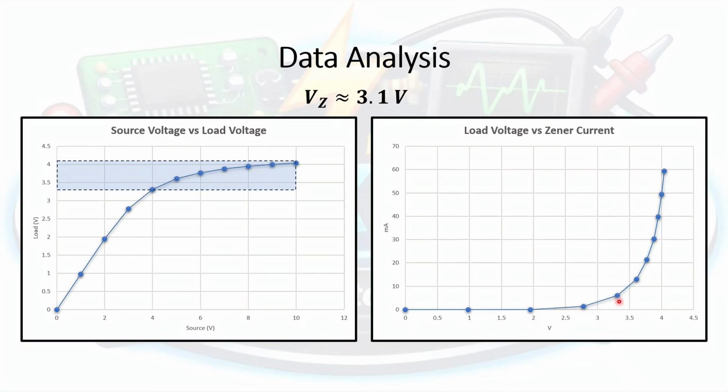However, when the voltage on the diode goes over the reverse breakdown voltage, as you can see in the graph here, the current increases rapidly. Now, an increase in current like that normally happens when there are voltage fluctuations on the input. Now, as you can see here, even if the current is increasing rapidly, the voltage across the diode remains fairly stable. Hence, the diode now, at this stage, is regulating the voltage across the load.